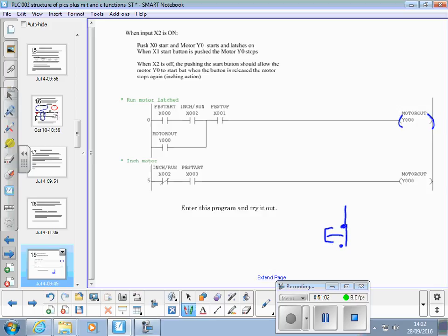They're done that way because that means it's fail safe. If your machine is running and the wire breaks off your stop button, the machine stops because you're losing that input. So stop functions are always wired normally closed in a loop. So if you break that loop, you actually stop the machine. It's called fail safe, fail to the safe condition.